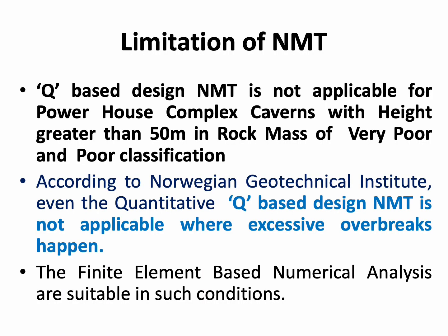Now, there are limitations of NMT also. The Q-based design NMT is not applicable for powerhouse complex caverns with height greater than 50 meter in rock mass of very poor and poor classification. According to the Norwegian Geotechnical Institute, even the quantitative Q-based design NMT is not applicable where excessive overbreaks happen.